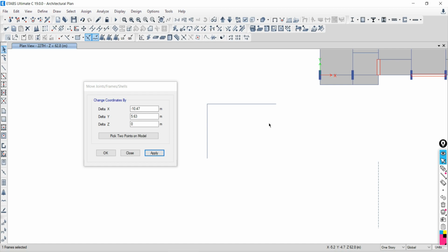After that nothing will be there. Just come here. It automatically catches the ordinate distance, x and y. Then simply apply. So it will be shifted from this to this side. Clear or not? I want to keep this beam from here in continuity of this beam. So select the pick point from this point to this point. Say apply. Understood or not? Clear.